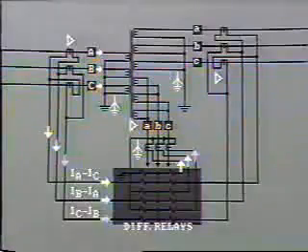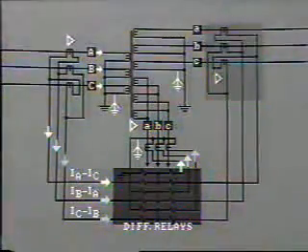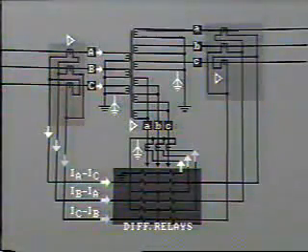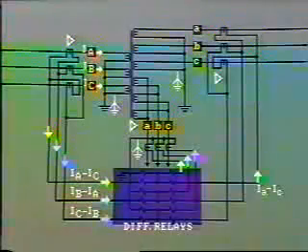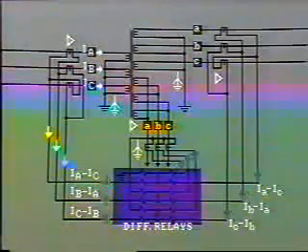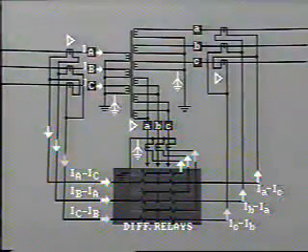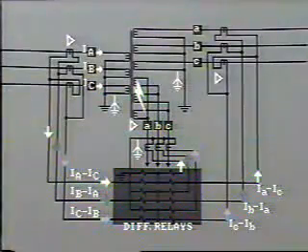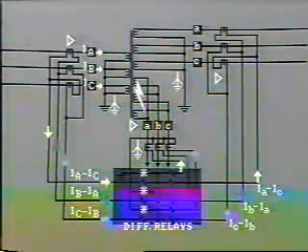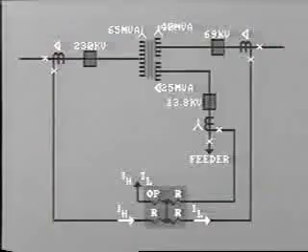The differential relays B and C have similar currents, and the current in their operating coils is also zero. Now, having checked the primary and tertiary windings, let's check the phasing of the CTs in the transformer's secondary. These are delta connected like the primary. Hence, like the primary, the currents from the relay are IA minus IC, IB minus IA, and IC minus IB. With balanced operating conditions, these three sets of currents cancel, and no current will flow through the operating coil. If an internal fault occurs inside the transformer, then out-of-balance currents flow in the operating coils, and the relay will trip.